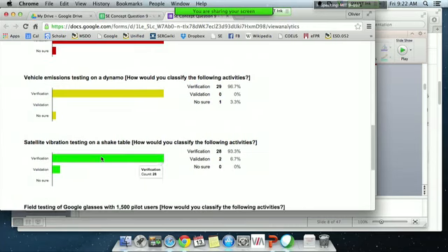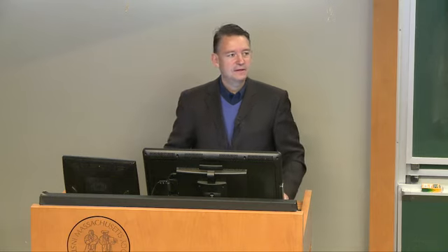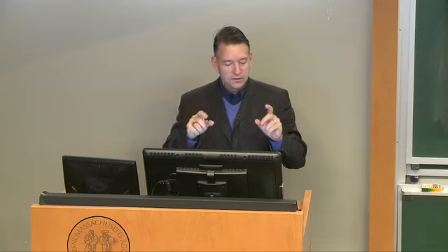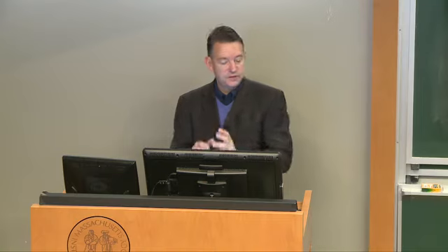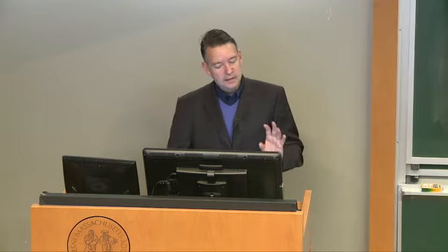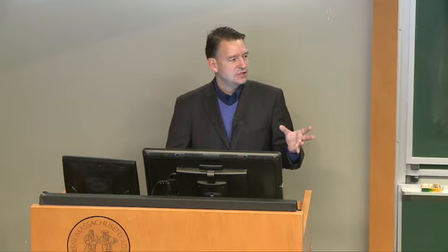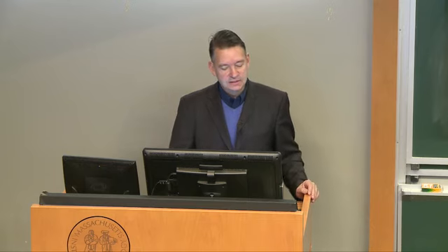Satellite vibration testing on a shake table. We'll talk about this. We often refer to this as shake and bake in the spacecraft business. The load spectra that are put into these shaking tables are, again, very stylized and different for each launch vehicle. So here we can debate a little bit whether it is closer to validation, because the actual test conditions are so much adapted to each launch vehicle. But I agree this is primarily a verification activity.